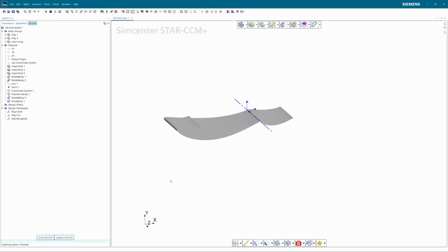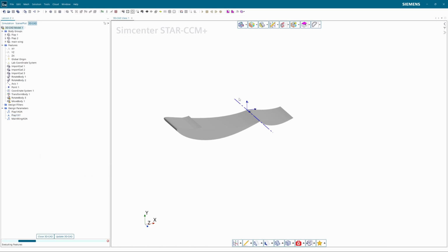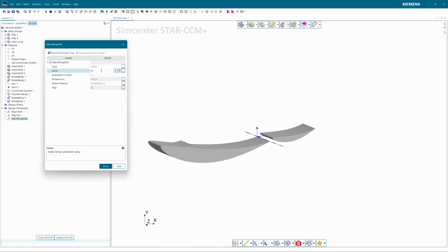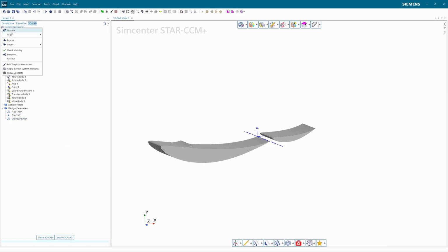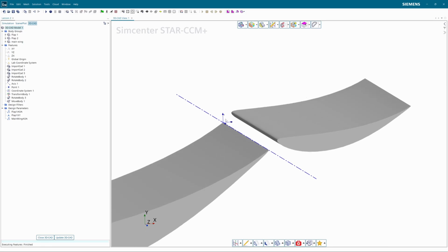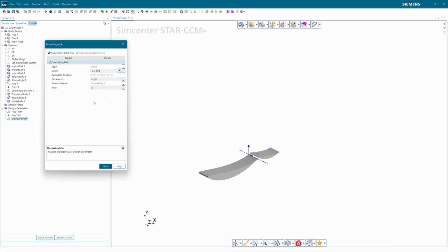All right, that will be that. So now you have these parameters here, and I'll show you what happens if I edit them. So if I edit this to, let's say, 10 degrees, and I edit this to be 1 centimeter, 1 centimeter, and then I update it, you will now see that this does this. And now the beautiful thing about this system is that when I edit this to be 15 degrees and I press update, this will move, but this will remain in the same way relative to this point, this axis and this coordinate system, which is why it's quite an elegant solution to this otherwise rather complex way of setting it up. Otherwise, it would require a lot more math and a lot more setting up, but this way everything remains quite smooth.